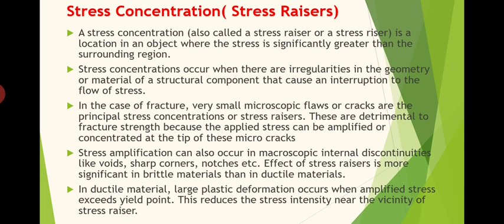In case of fracture, very small microscopic flaws or cracks. Flaws actually means microscopic levels of cracks, in simple words. In case of fracture, very small microscopic flaws or cracks are the principal stress concentrators or stress risers. In most fractures, as I have already told, these flaws or cracks act as the principal stress concentrators and contribute to the failure.